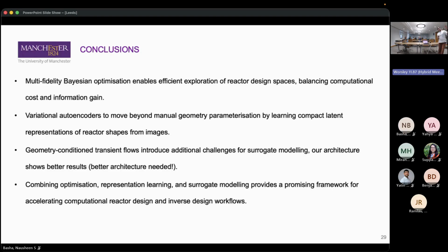And then finally, we look into much more complex surrogate models developed for these kinds of problems with two-phase flows. In most cases in two-phase flows there's an adaptive mesh, just because if you train on a really fine mesh of millions of cells, that would be a crazy amount of machine learning training. First, there would be challenges in generating the data, and then even if you have the data, it would be a crazy amount of training. So how do we make it work on something like an adaptive mesh, which is an efficient way to generate the data and also do the training? And in future, how can we combine all of this into a more comprehensive workflow in order to explore really clever, really counterintuitive shapes?